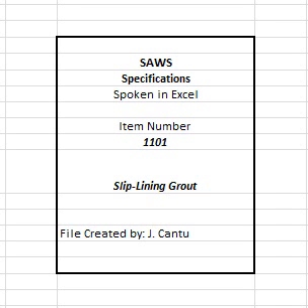During grouting operations, the recorder shall continuously record the actual grouting pressure versus time on paper with ink. The gauge shall conform to an accuracy of 0.5 psi. The range of the gauge should not be more than 100% greater than the design grout pressure. Pressure gauges shall be instrument oil filled and attached to a saddle-type diaphragm seal, gauge saver, to prevent clogging with grout. All gauges shall be certified and calibrated in accordance with ANSI/ASME B40.100-2005, Grade 2A.